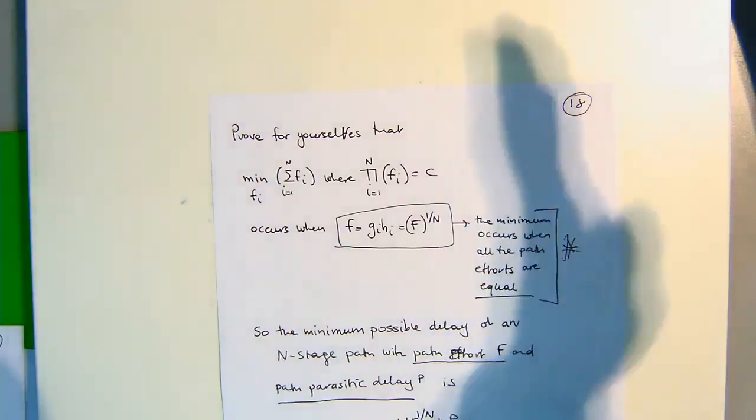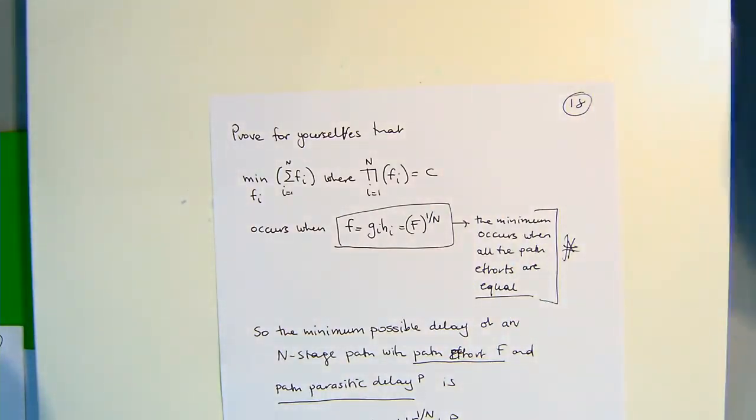If you want to implement a particular logic function, you've got no choice. If you're trying to build an arithmetic logic unit, you can't change the logic. You can implement the architecture a little bit differently, but let's assume that you've chosen the optimal architecture. The only thing you've got available to you is to size these gates so that you get the minimum delay, and therefore the highest performance. So the question is,